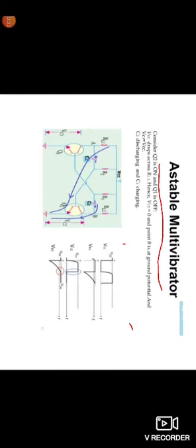It moves towards the capacitor C1, so capacitor C1 is charging, and it is charging towards the base of Q2. And when VCC is applied, Q2 acts as a short circuit, so capacitor C2 is discharging through point B to the ground terminal.